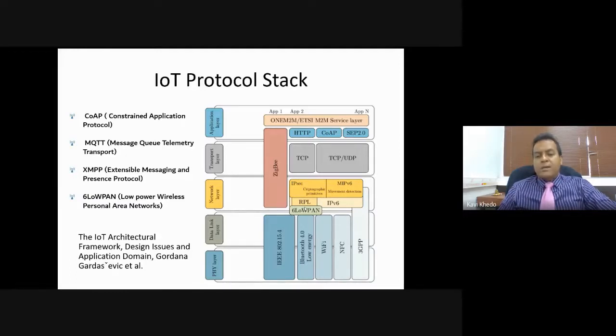Whereas we are talking about IEEE 802.15. As soon as you see 802.15, the .15 means low power. You associate the idea of low power with all technologies that normally follow .15. Actually, Bluetooth is IEEE 802.15.1, which is still low power, but 802.15.4 is even lower in terms of power consumption.